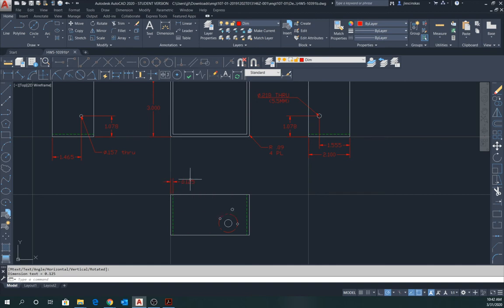This is an extrusion. Remember, this is an open area, and this is made from extruding a piece of aluminum. So the thickness here is whatever the part comes out to be. It's not necessarily 100% exact, and the tolerances tend to be rather wide. It tends to be more on the order of 10 to 20 mils than 0.005 that you would normally expect.